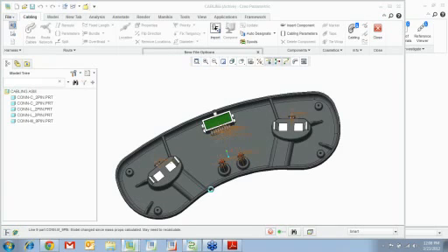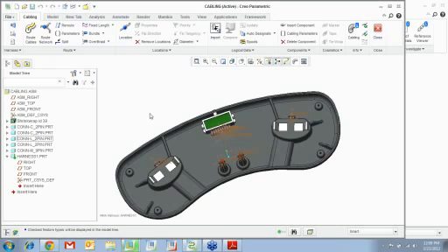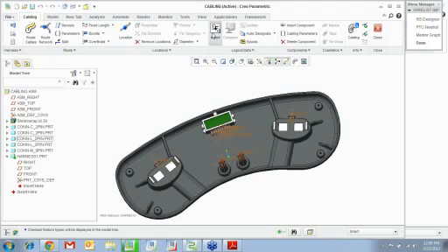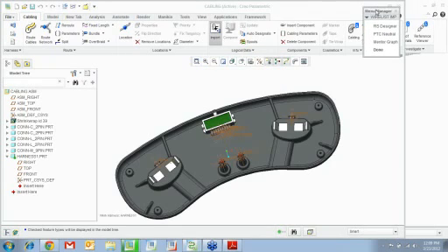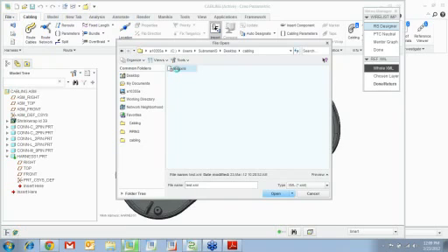Millimeters. Now once I create the harness, I want to go ahead and enable the features so that you can see what's in there. See that? It's a harness part. Now, the first thing we're going to do is import this XML file. How do we import this? You have this icon right here. Click on that. You're going to say RS Designer, which is Routed Systems Designer. This is what it used to be called earlier. You want to import a whole XML or just a part of it. I'm just going to import the whole XML. I'm going to browse and pick that test XML.